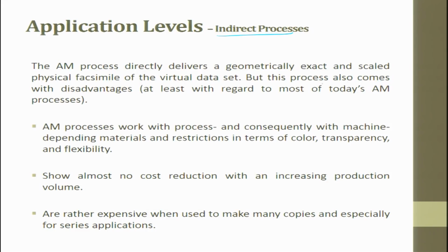but this process also comes with a disadvantage, at least with regard to most of today's AM processes. AM processes work with process- and consequently machine-dependent materials and have restrictions in terms of color, transparency and flexibility. They show almost no cost reduction with increasing production volume, and are rather expensive when used for making many copies, especially for series applications. So, these are some of the disadvantages when we talk about AM processes today.